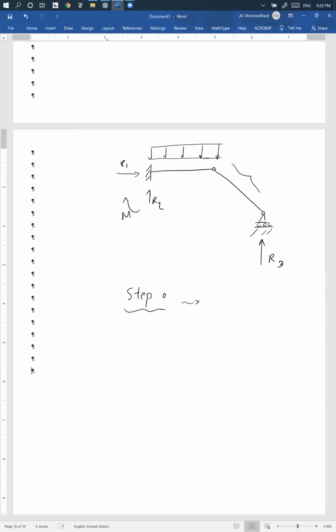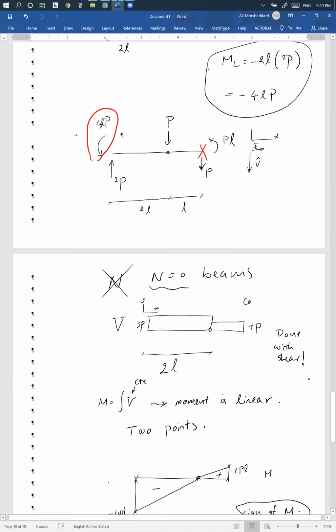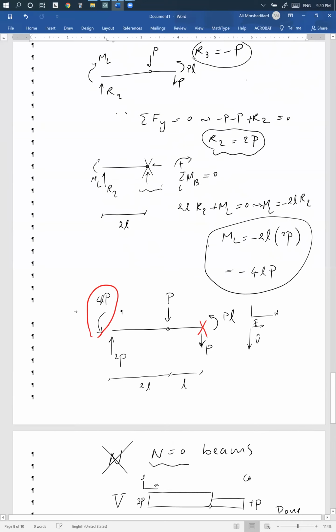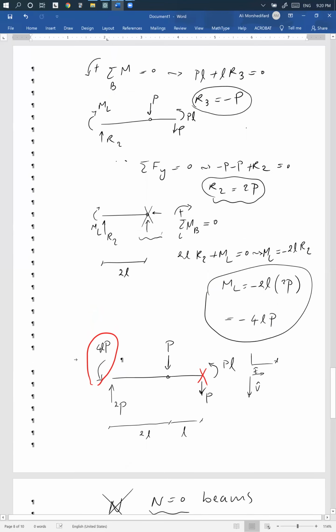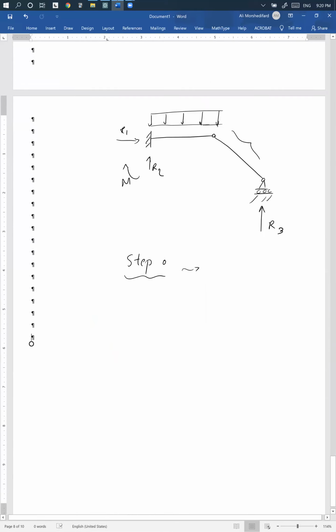Do you remember that this problem we solved earlier? Exactly this problem, right? How did we handle this pin? It's basically the same. Whenever you have these pins, you separate them at the pin and use a moment about that pin. I think I can say that that's always the case. So again, if I separate this right side, exactly like the previous problem, F1, F2, you see, if you practice, these issues keep repeating themselves, right? They are finite.